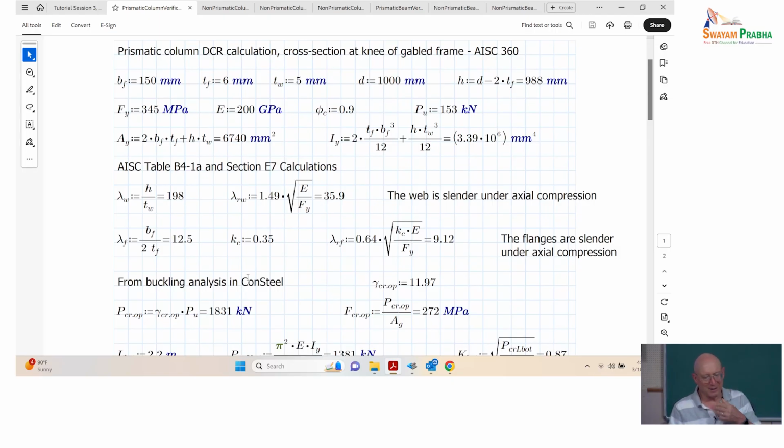non-slender plate limits. If I say I have a slender flange or a slender web in axial compression in AISC, what does that mean to you? Did you get that takeaway from last week yet? Crickets. Okay. Slender web or a slender flange, what does that tell you in terms of characteristics of the plate? Width should be reduced effectively. The width should be reduced. If you want to make it more efficient, possibly, yes.